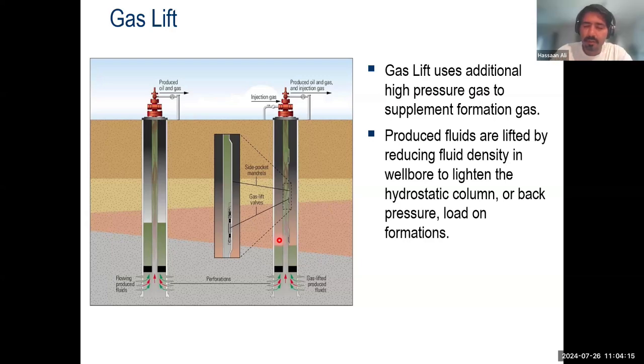Solids have absolutely nothing to do with the wellbore pressure. But solids have something to do with the gas lift system. One of the advantages of gas lift systems is that they are very tolerant, very flexible in terms of solid production. Solid production is actually a big problem in artificial lift systems, because solids can damage other means of artificial lift, for example progressive cavity pumps, electrical submersible pumps, and rod pumps. By solids, I would categorize sand production, but there could also be debris, paraffins, and scale, all of those things that can affect our wellbore or the production of oil and gas.